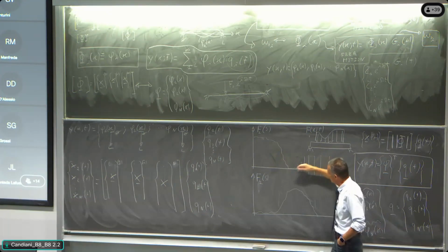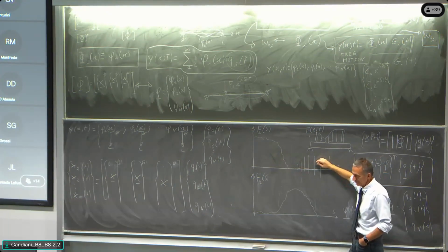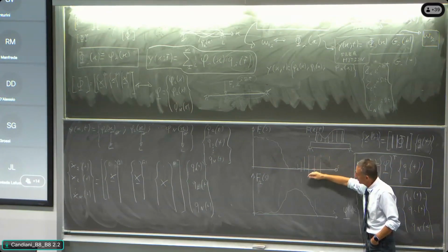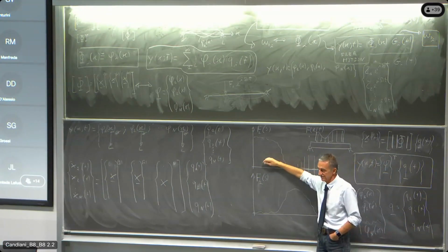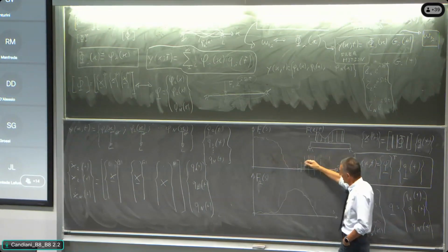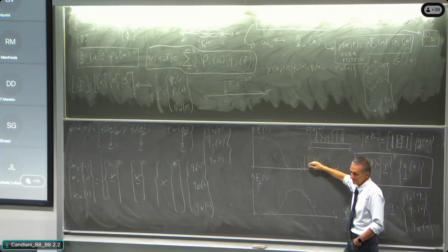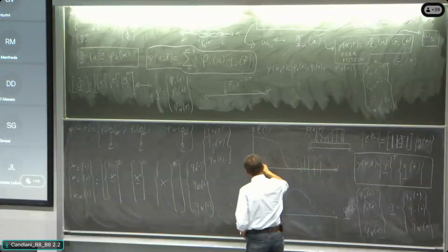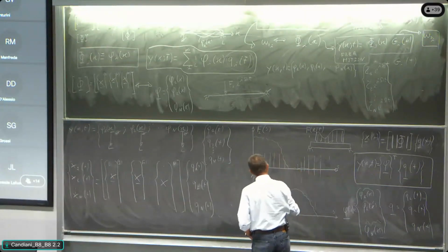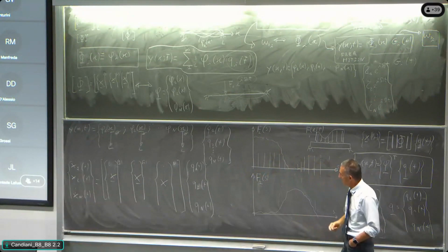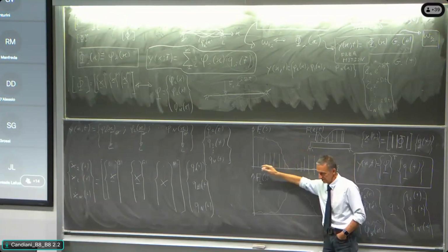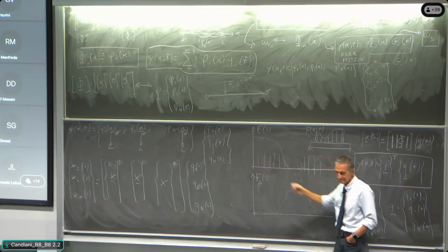All right, so we know that the system answers strongly when the spectrum of the excitation meets the frequency of the modes. And so the modes that are here, it is useless to model them if the excitation is there, all right? I can do it, yes, but they will not participate. What is fundamental, if the spectrum of the excitation is this one, is that the modes having a natural frequency inside the bandwidth of the excitation are modeled, all right?